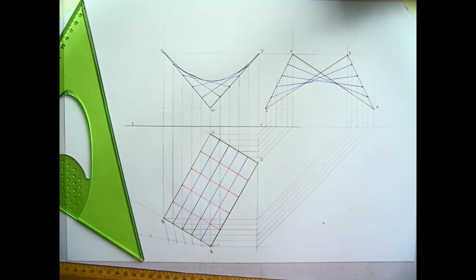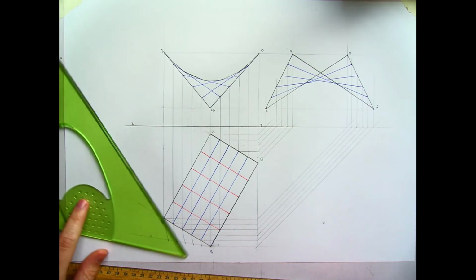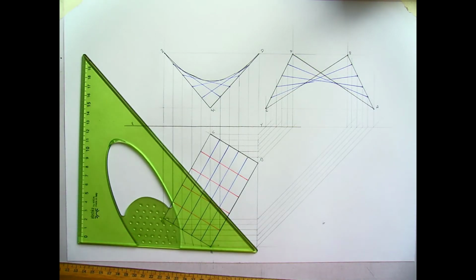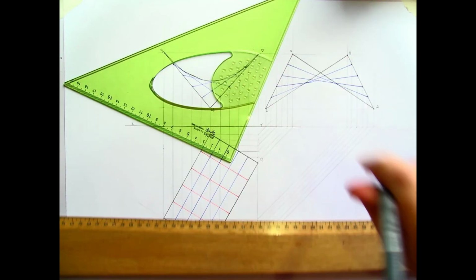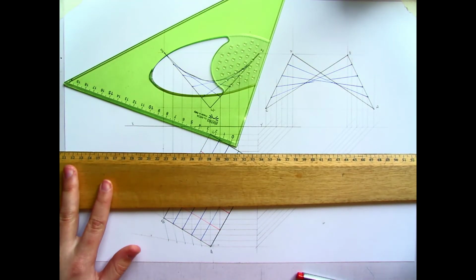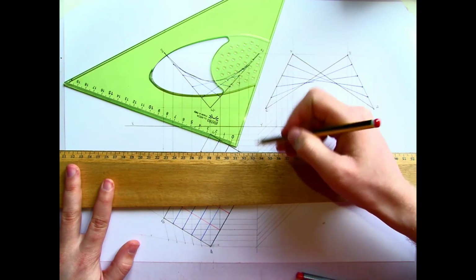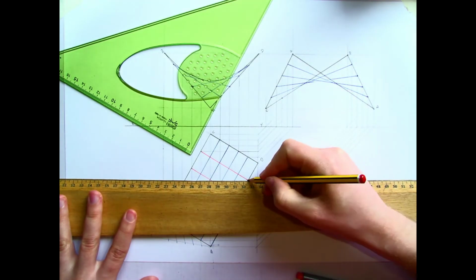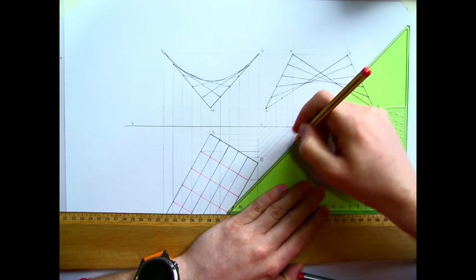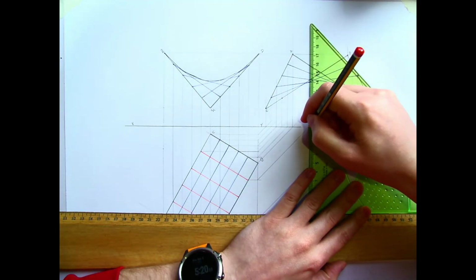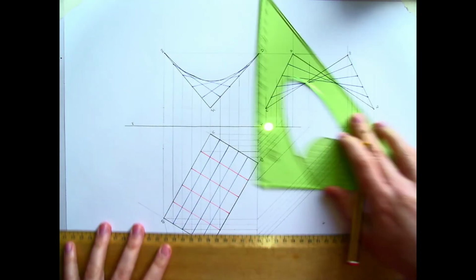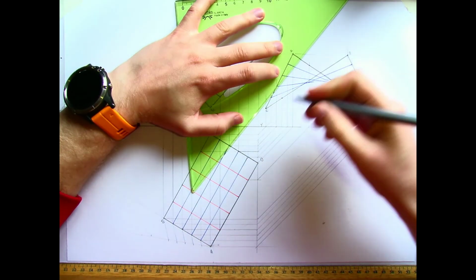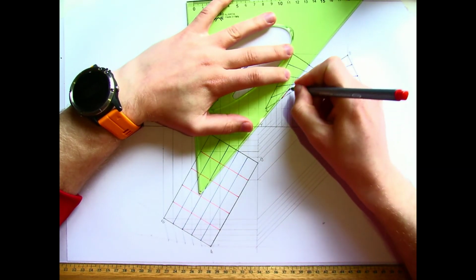Now we need to do the same thing with lines joining BC and AD, so the red elements. They're again going to need to be brought over and up into the end view. The heights are going to be the same as they're in the elevation, but we can do them this way. So line has to come across. This is going to be at the same position here. So where this one came up, that's one point. The other end of this line, which I don't have yet, on the line AD, is going to be that point up there. So on the line CB to the line AD.